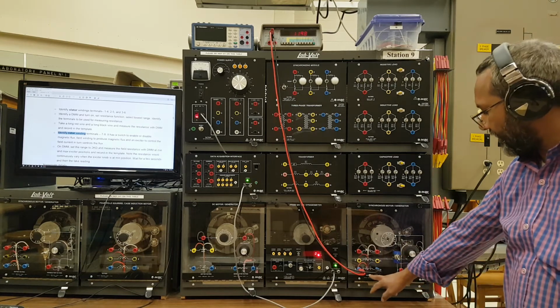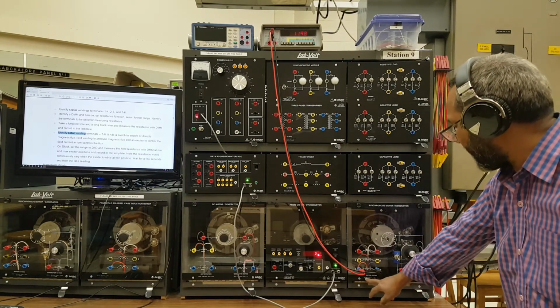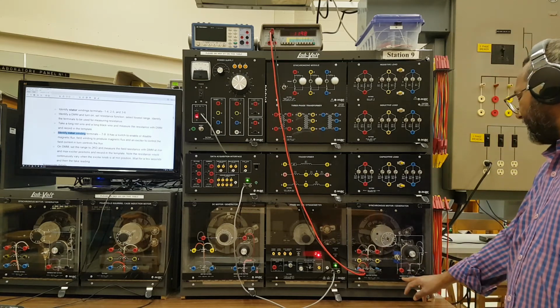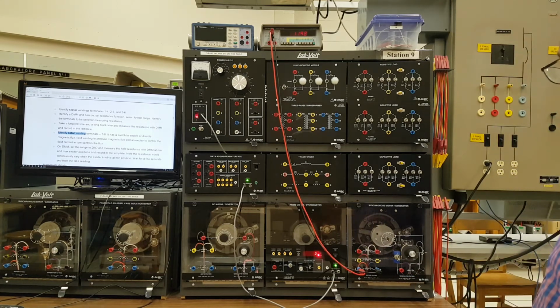And you can see here there are motor ratings on the left-hand side, and the generator rating on the right-hand side. So basically the values would be the same except the current rating. The power rating is different also: 175 watts it will give you as a motor. And the speed should be the synchronous speed, 1800 rpm, for both. It's the same thing, 208 volts.